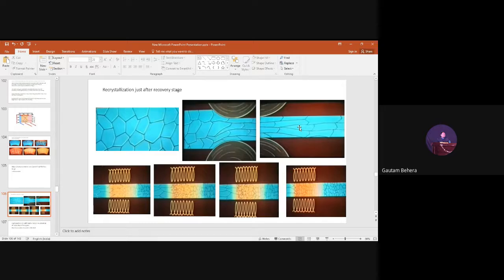Nobody is saying. What kind of grain structure is this? This one is equiaxed. What kind of grain structure is this? Elongated, yeah, elongated grains. In which direction have they elongated? Metal flow direction. Yes, metal flow direction or rolling direction, where we are doing rolling on this.